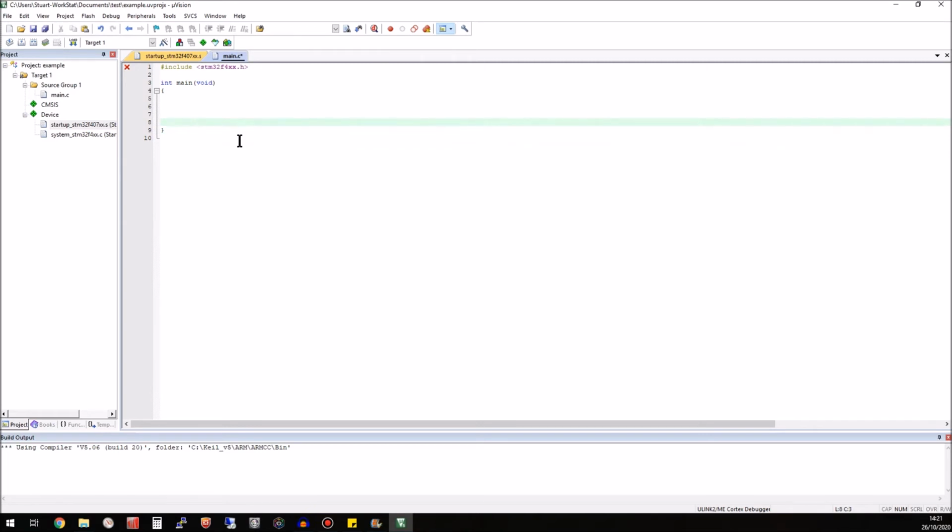When the microcontroller begins to execute code within the main function, it will start at the top and work its way down through the successive instructions. It must not be allowed to reach the end of the main function. If it does so, the microcontroller will go into either a reset or an error. To prevent this from happening, a while loop is put in place, like so. A while loop will continue to loop as long as the condition within the parentheses is met. In this case, I have simply put a 1, which means that the condition will always be met, regardless of all other activity.